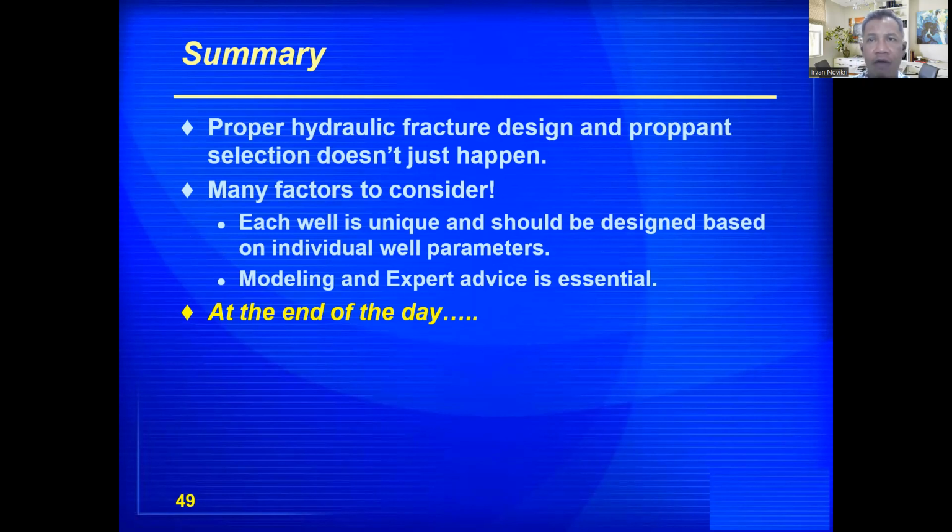It takes knowing the formation, so you understand the direction to drill and the direction the frac is going to go, and that you have the right proppant, because some of these shale wells that we have today are going to last over 40 years, longer than just about most people's careers. And so the proppant that we place in there, in the fracture, has in most cases to last the life of the well.